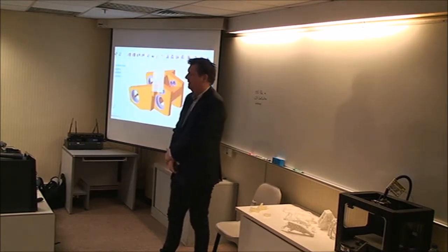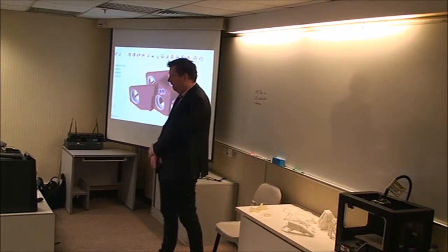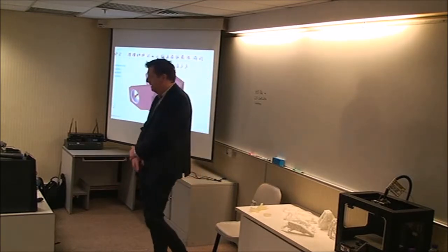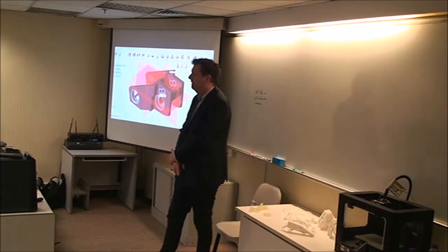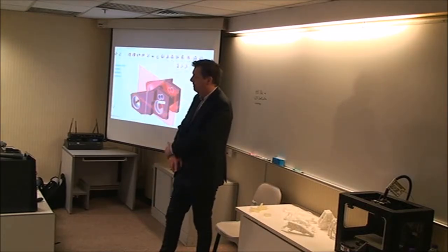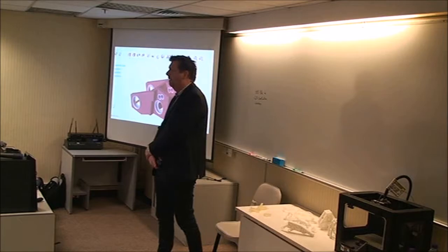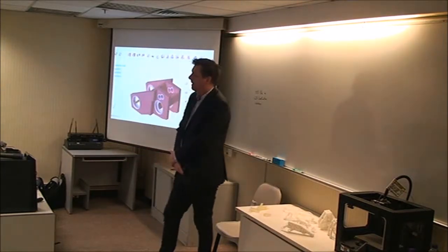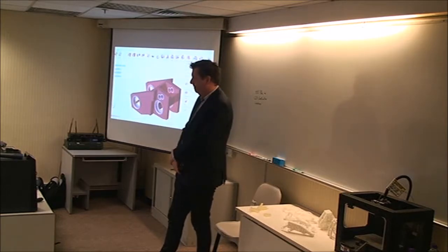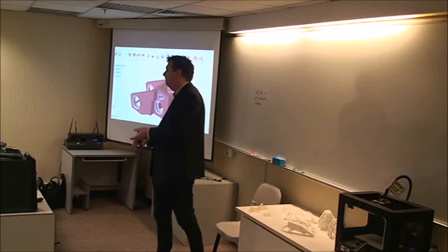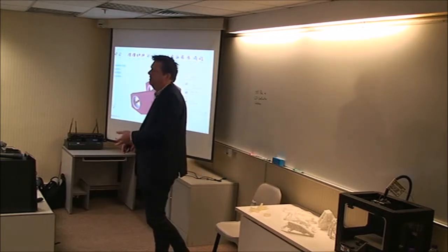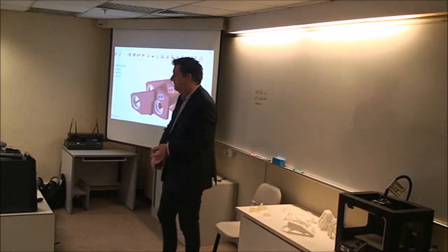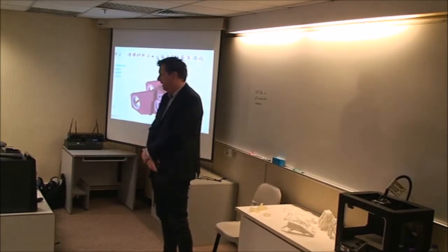And once you've got that, your loads are still in your model there. This is setting up a symmetry constraint. So again, very simple graphical representation of stuff. No complicated menus to learn. Everything's just up there in the little icons on the top. Run it again. Do design exploration. Look at it using different amounts of material. Look at it using different stress constraints. You can change your package space, and you can